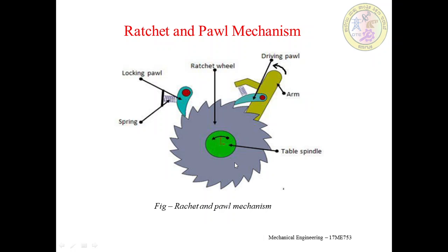Ratchets consist of a gear wheel and a pivoting spring-loaded pawl that engages the teeth. These are nothing but different teeth. The teeth or the pawl are at an angle so that when the teeth are moving in one direction, the pawl slides between the teeth. The spring forces the pawl back into the depression between the next teeth.